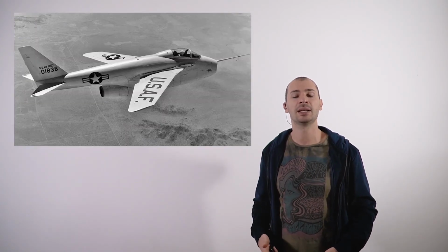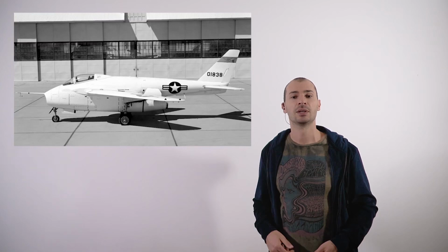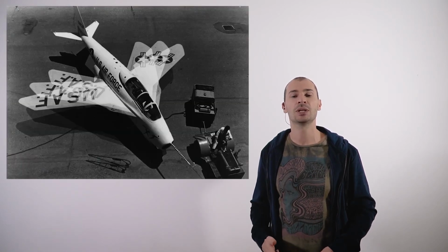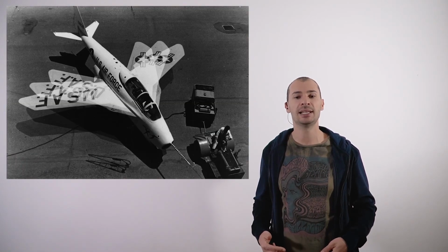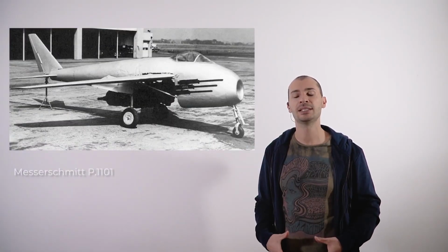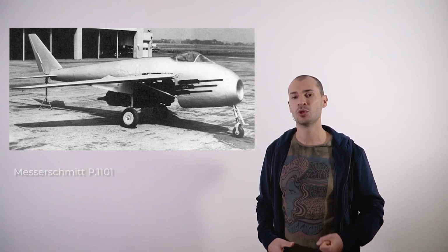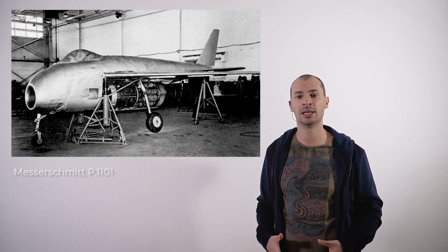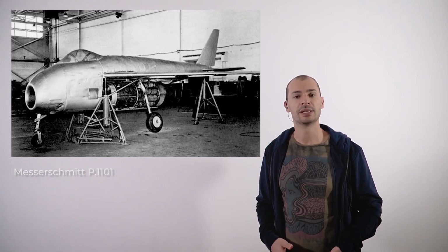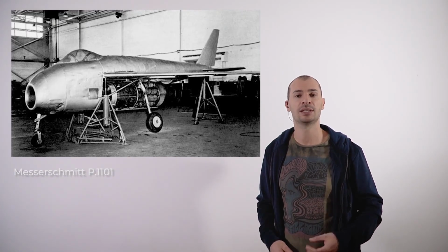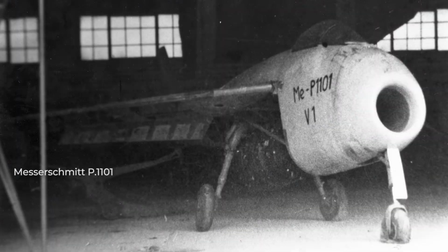In this case, I'll tell you something about the Bell X-5, which, as Sergio said, is the first plane that could change the geometry of its wings in mid-flight. Its roots originated in the German design of the Messerschmitt P1101, from which the X-5 borrowed a lot in terms of overall design. The Messerschmitt P1101 was considered the ancestor of variable geometry wing aircraft, since it could vary its wings at a sweep angle from 30 to 45 degrees.